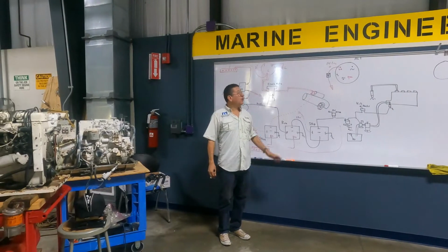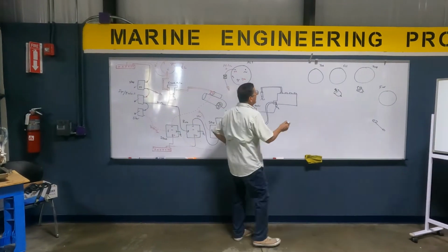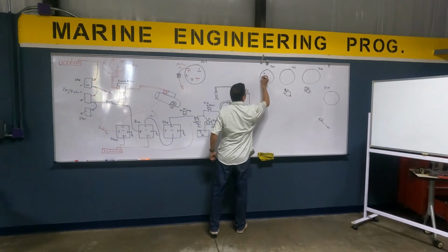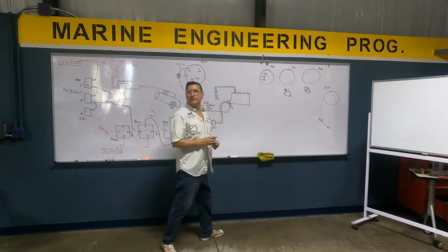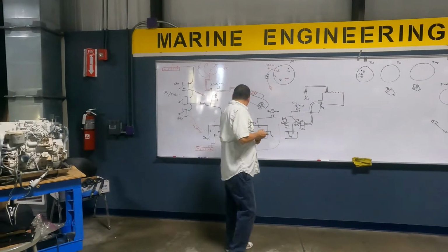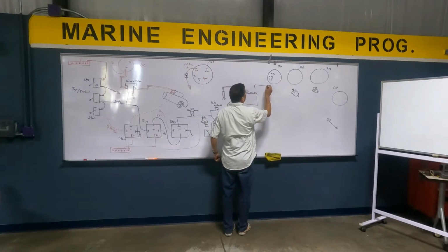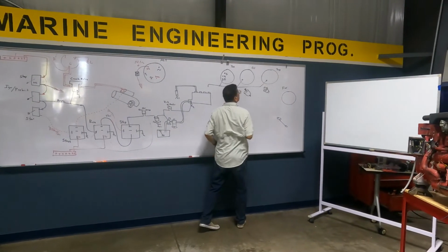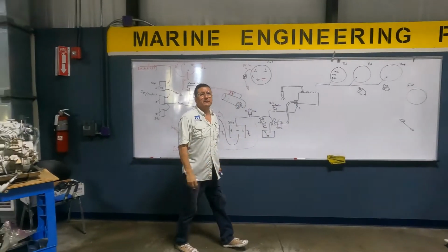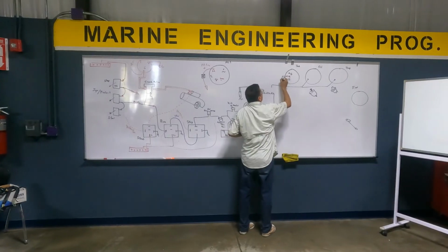Right, now guys? Okay, we are going to connect the tachometer. You remember the tachometer has 3 terminals here. One terminal is signal, ground, and ignition. You remember? Of course, ignition is the same purple cable. It enters here and activates ignition for this, and for this. Ignition. What about ground? Ground is ground, no problem.